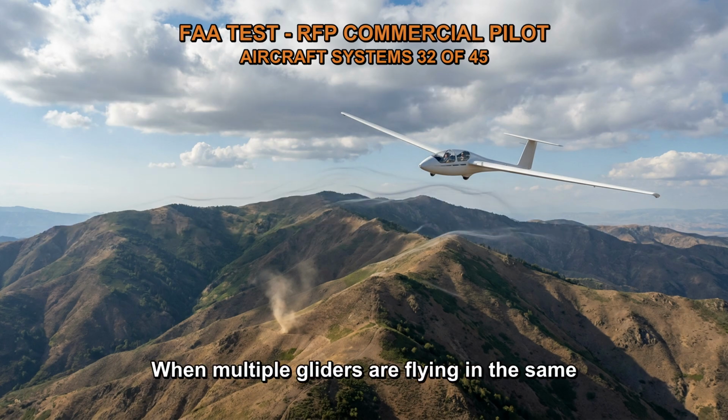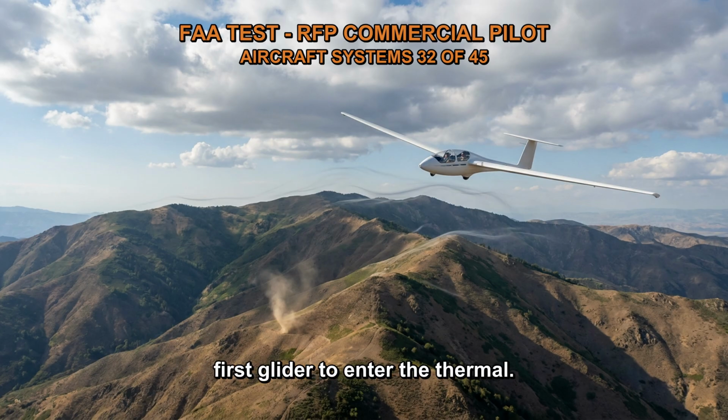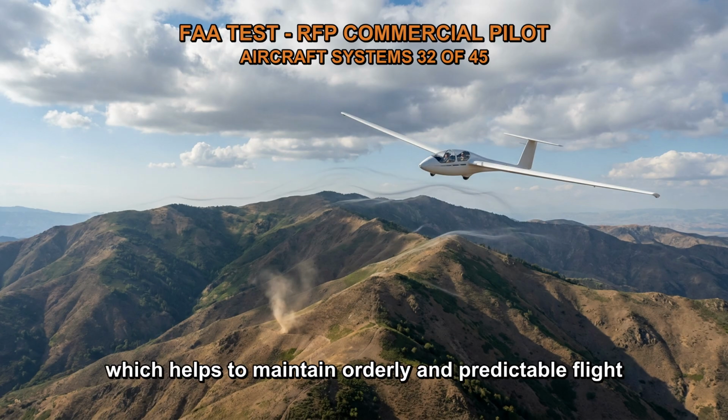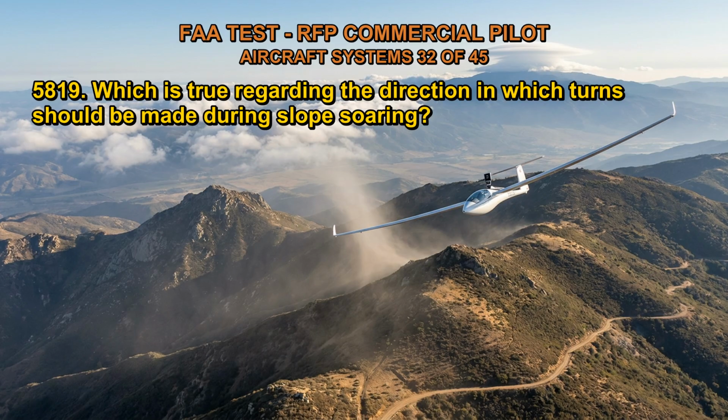When multiple gliders are flying in the same thermal, the general rule is that turns should be made in the same direction as the first glider to enter the thermal. By following this convention, all gliders in the thermal will be turning in a consistent direction, which helps to maintain orderly and predictable flight patterns. It reduces the risk of collisions and improves overall safety.